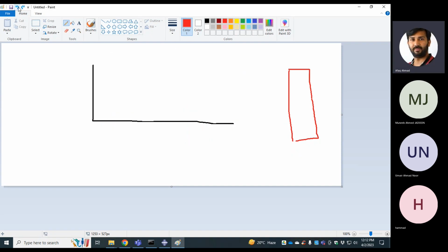However, we have another type of dynamic analysis, which is time history analysis or real earthquake data. In that case, we do not have a uniform lateral load or uniform cyclic magnitude. So the shape of this one is like this. You have some small value of the PGA, peak ground acceleration, then you have some higher value, and then again some small value, and then some higher values.